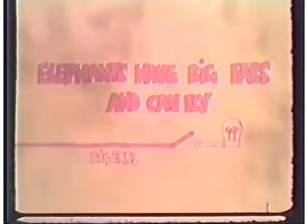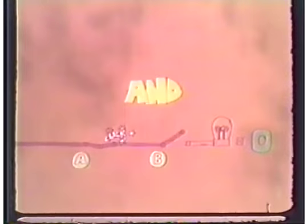Logical statements are either true or false. These can be shown by 1 and 0. Elephants have big ears is true and equals 1. Elephants can fly is false and equals 0. Elephants have big ears and can fly is false and equals 0. This is the AND switching circuit.